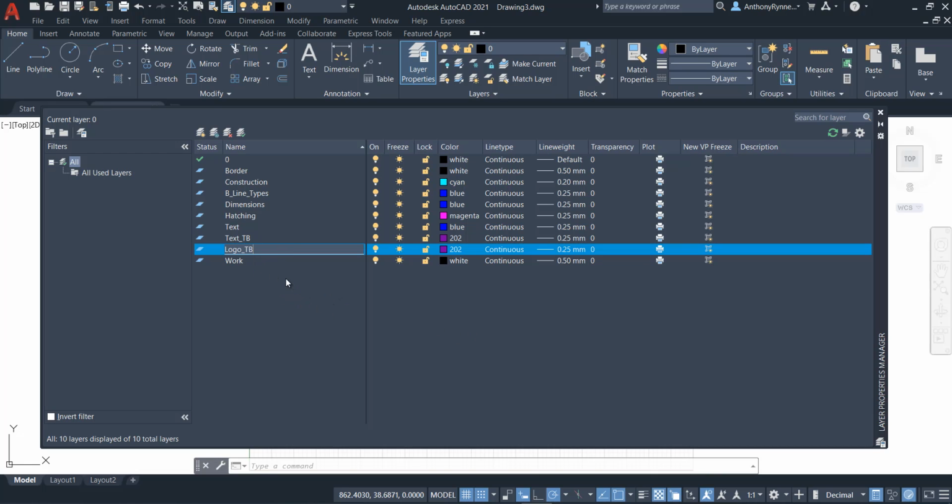And this kind of thing you often find on architectural drawings, whereby they use like A for architect or B for building, whatever, to group layers together. So you can use something called filters, and AutoCAD provides 2 different filter types. You can have either a property filter or a group filter if you want to select multiple layers.